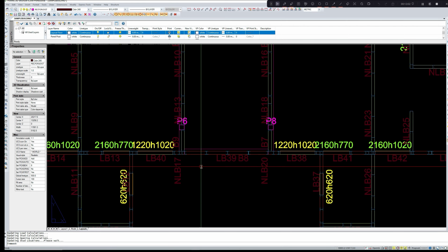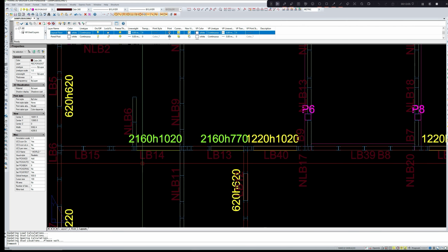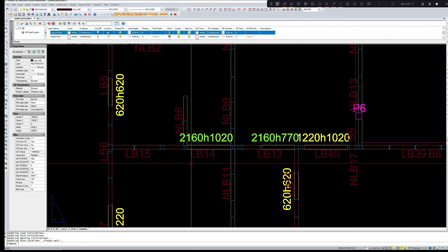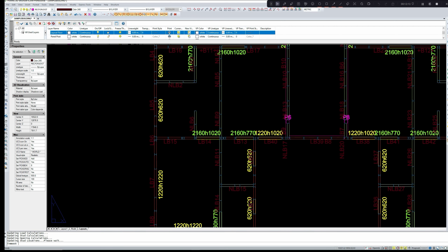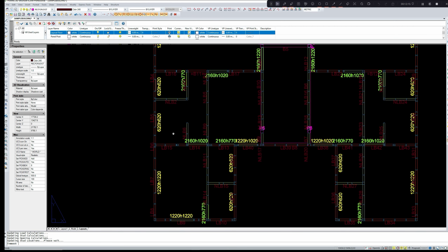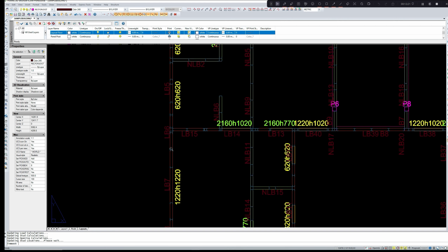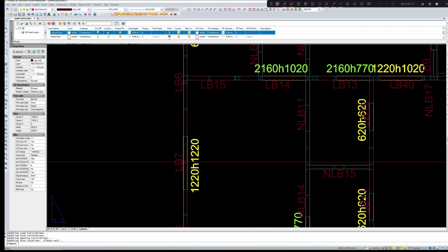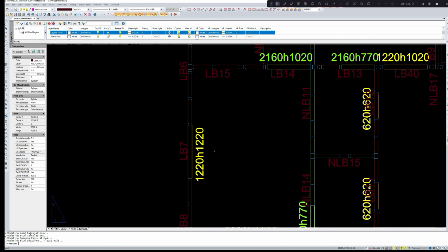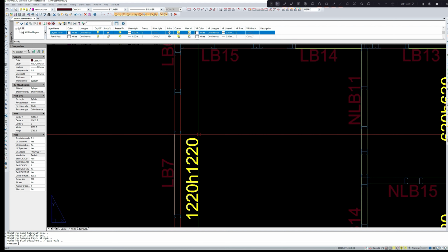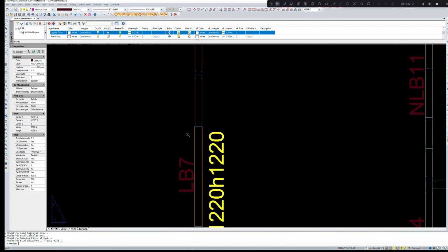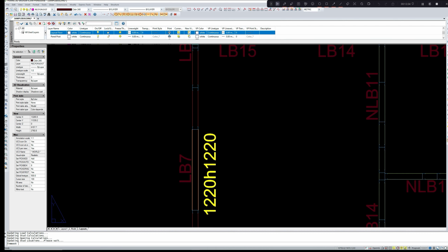You can see the studs have been provided. For load bearing walls there are double studs, and for non-load bearing walls there are single studs. We can change this because these side walls will not carry much of the joist. Now see, at the opening there is only one joist, so we should check that also. We should provide the number of joists for the jamb stud.